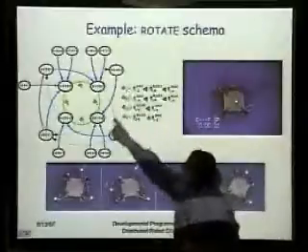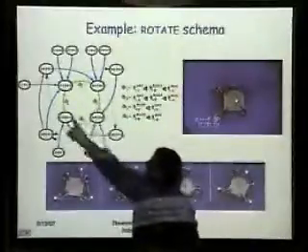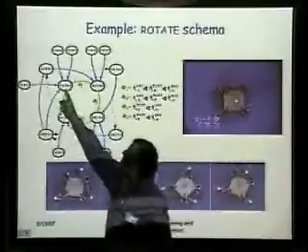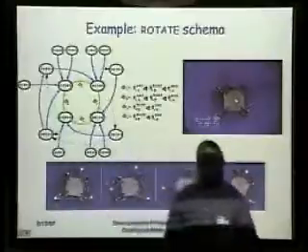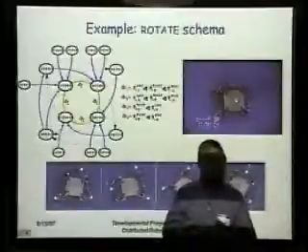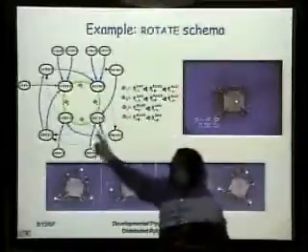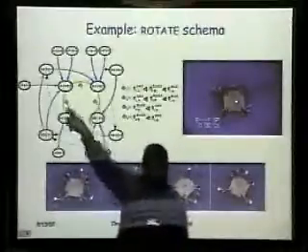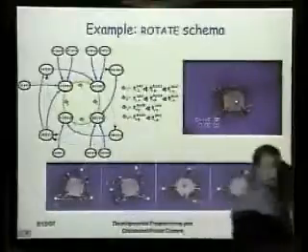These are the actions that go around this central 4-step gait. 95% probability if you're in this state and you enter that action that you'll go to this one, and so forth. The green denotes transition probabilities in excess of 95%. The blue ones are lower probabilities and less frequently visited states. And so if you were to bump into a curb, it would take you off over here someplace, and the greedy policy gets you back into the main cycle. So it's a program with contingency plans built around what it explored, and it's now a macro, and we're going to call this a controller, put it in the control basis, and say, if you'd like to configure that controller and use it instead of the primitives, go ahead.